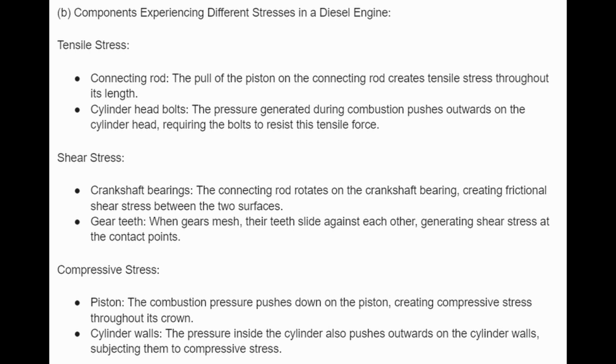B. Components experiencing different stresses in a diesel engine. Tensile stress. The connecting rod. The pull of the piston on the connecting rod creates tensile stress throughout its length. Cylinder head bolts. The pressure generated during combustion pushes outwards on the cylinder head, requiring the bolts to resist this tensile force.